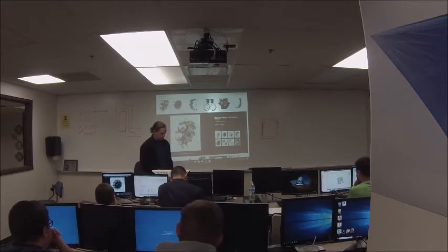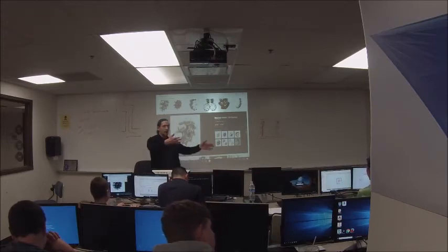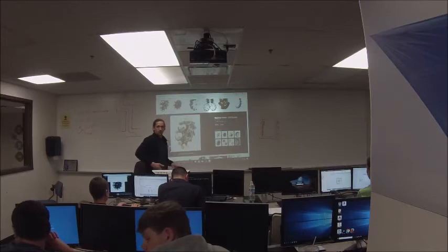The next thing is what's called an H drive. It's also called a slide drive. And effectively, it's similar to tank, where you've got wheels on the side of your robot like you normally would. You drive it like a tank. And then you also have